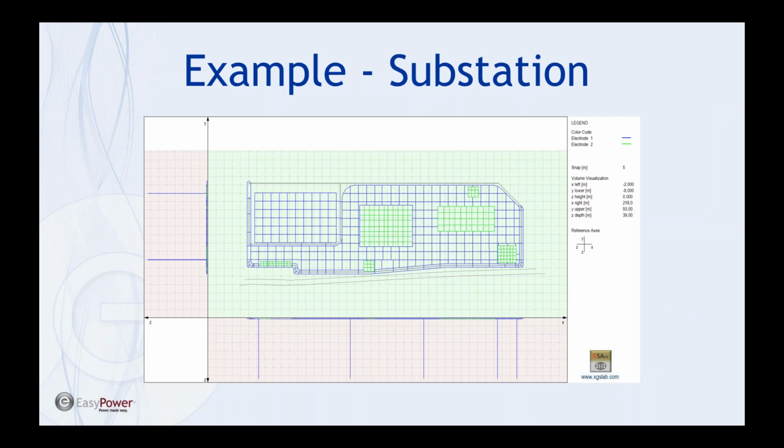So jumping right into examples now, we can see an example substation layout, grid layout. This is just showing the below grade conductors for a substation. We're not modeling anything above grade at the moment. The blue is the grid, so consider that maybe 4/0 copper or something like that. And the green are the foundations. And you can see that the foundations in this case are bonded to the grid in certain locations.